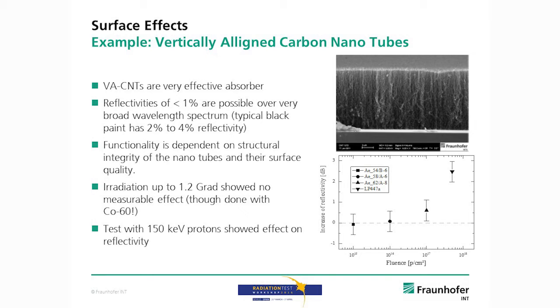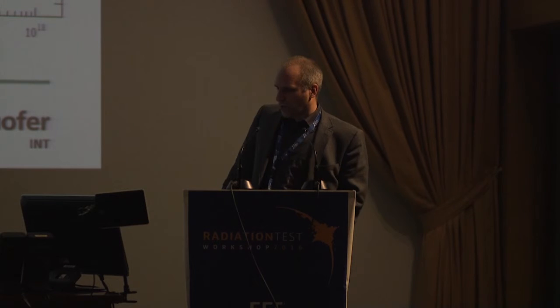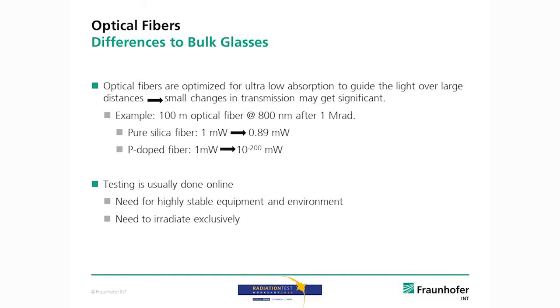We put them in the cobalt-60 facility, which is not what you should do for surface testing, but it was quick because we had them in-house, and we went up to 1.2 gigarad and showed no measurable effect, which wasn't quite expected. And then we went to low-energy protons at an implanter facility, and after a fluence of 10 to the 17, you see a significant increase in the reflection during the measurements.